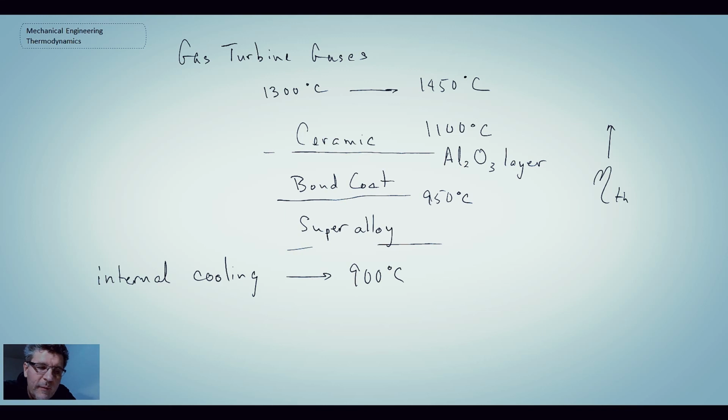It comes with a little bit of a challenge though, because as you get to the higher temperatures, you can start getting NOx formation. NOx is something we will look at when we consider combustion, and you need to be careful there because that is a pollutant. And so that would come back to the engineers working with the combustion chamber, and they would have to do designs there in order to reduce hot spots and reduce NOx formation. So these are the balancing acts that people who do gas turbine engine design would be involved with as they try to drive the thermal efficiency higher and higher.